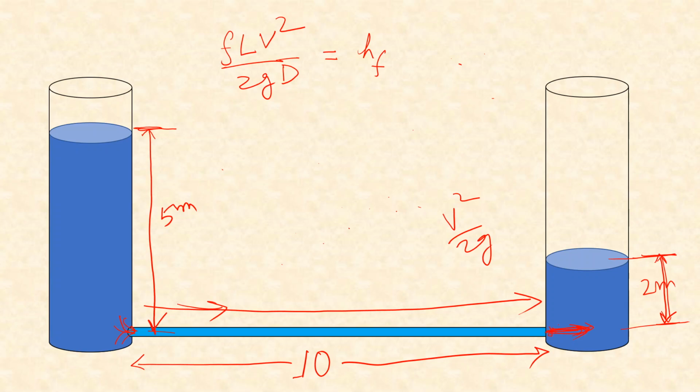That head will be lost because this will cause some turbulence in the static water here, and that turbulence will after some time die down, and by viscous dissipation that movement will be lost and the energy will be spread or leaked to the surroundings in form of heat, vibration, sound, etc.